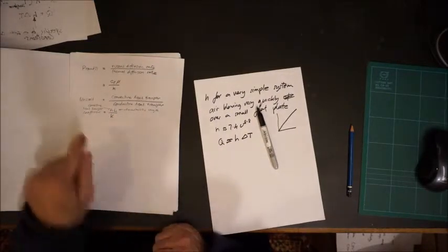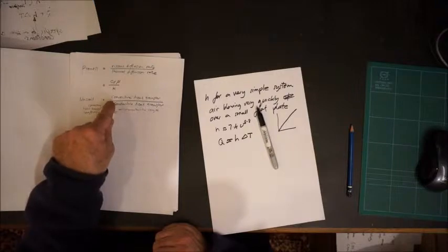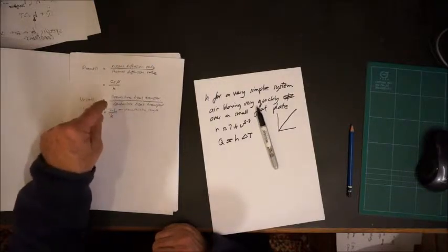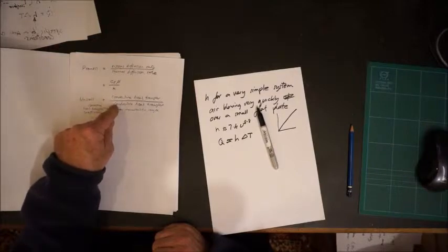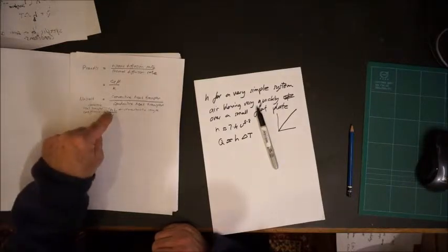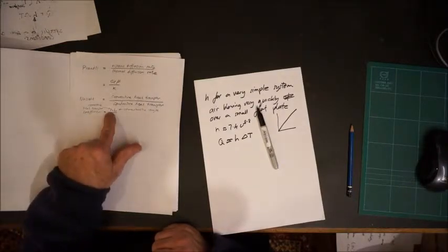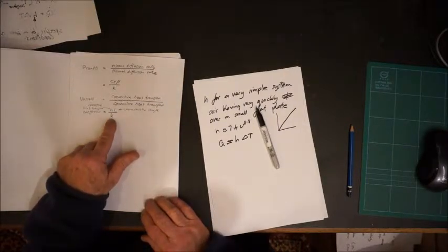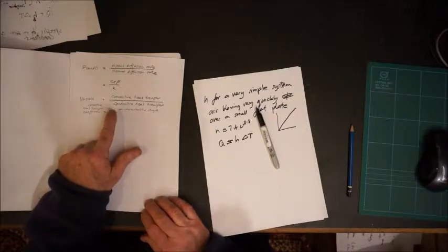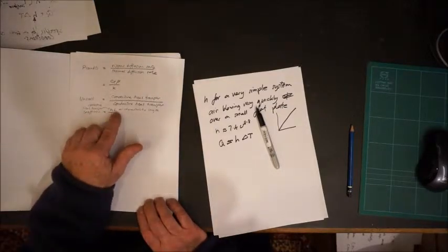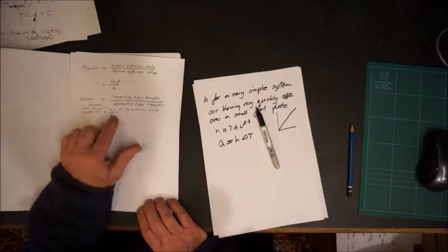And there's another number, a thing called the Nusselt number, which compares how quickly heat is convected away versus how quickly heat is conducted away. It's somewhat similar, but in this case here it's the convective heat transfer coefficient, which we've talked about, times the characteristic length, again by the thermal conductivity. The characteristic length is something that we use in a Reynolds number. Remember Reynolds number? And depending on what we're looking at, we can define this.